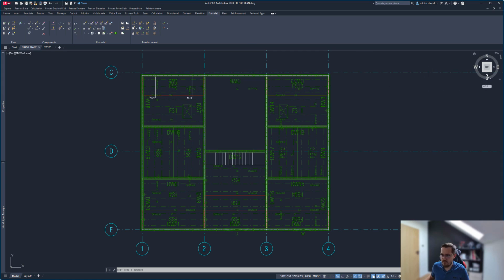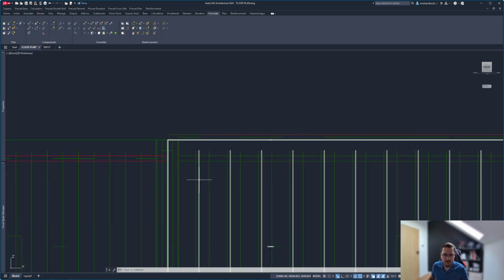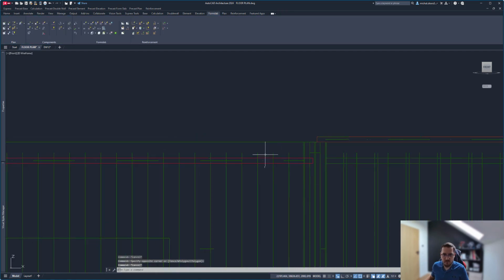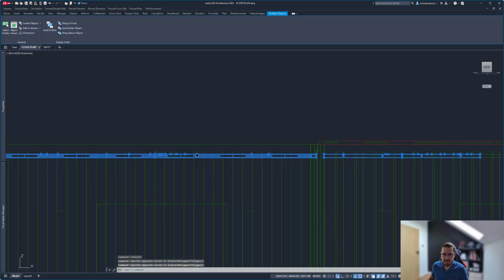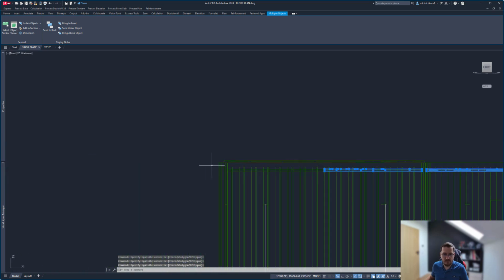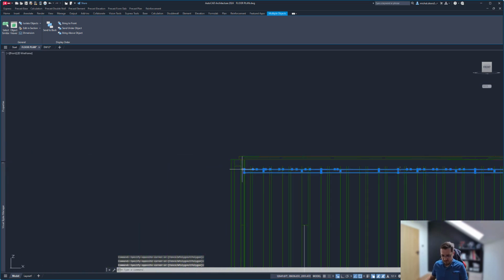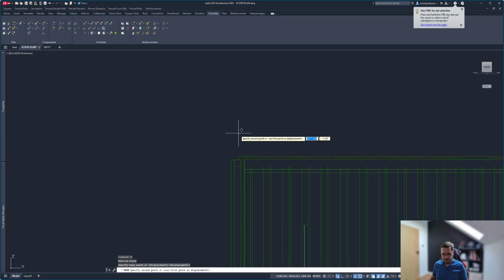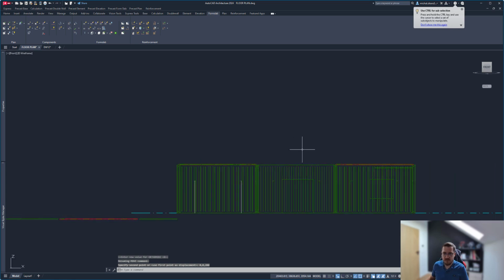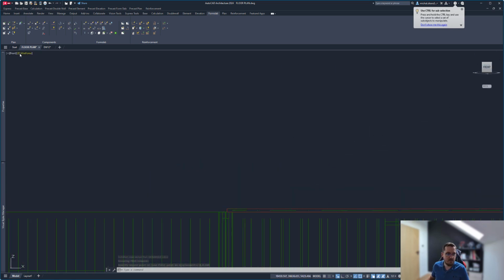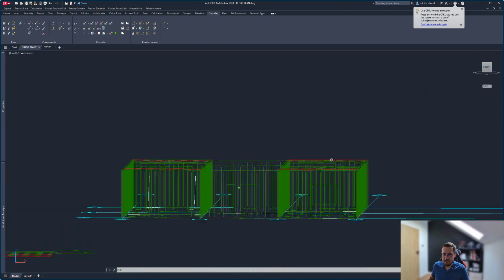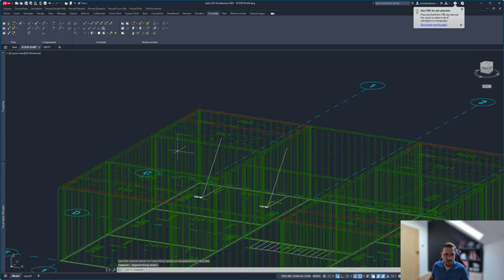And with that, I'll just move to the front view and check the slabs that are too low. So those are the slabs that we want to move, and those as well. What I'll do is move them by displacement. So we're going to use 0 displacement, 0 here, and 200 to the top, and that's perfect. So all our slabs are now at a proper level. Yep, they are good.